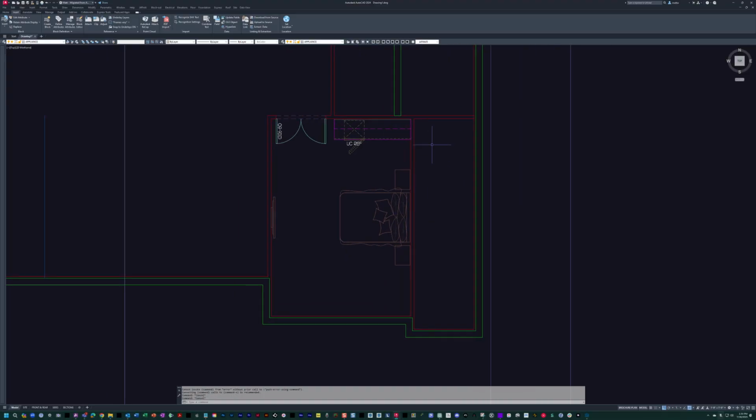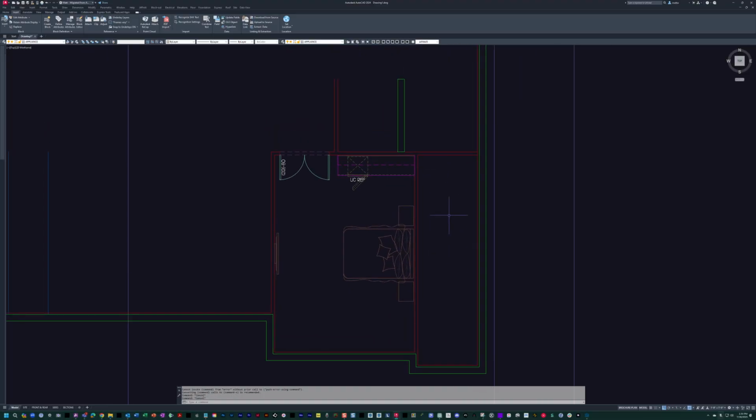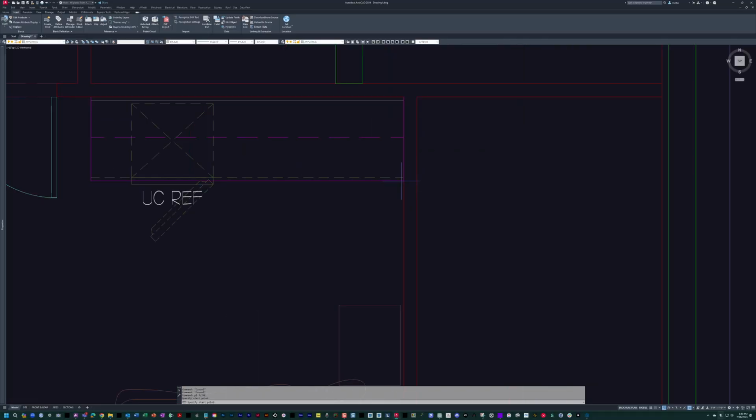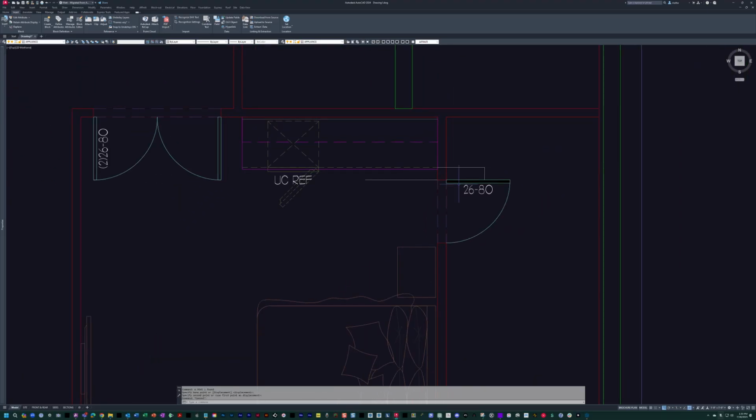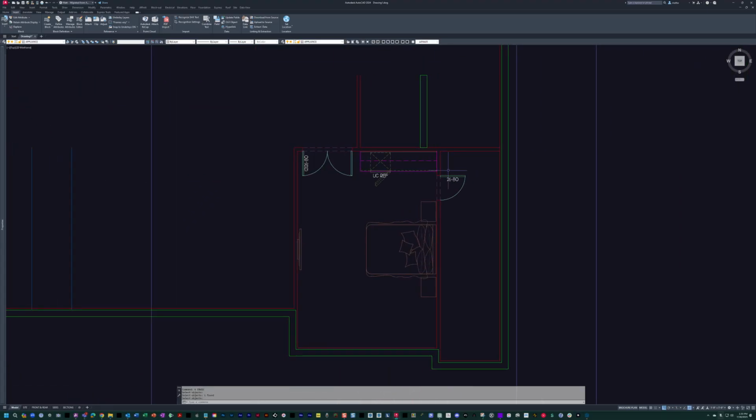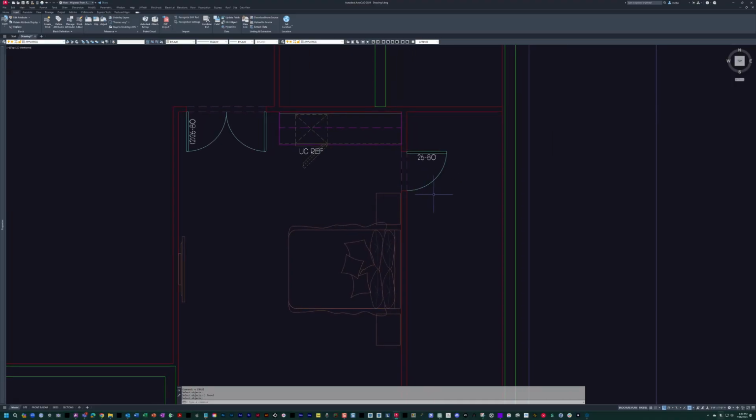I know we have a bathroom and a closet over here. I know already if this vanity is going to be here, again, I want a 6-inch jamb, so let's throw a door in here and see what happens. Maybe we'll have the door open the other way. Grab this and place this here. And yeah, we're clear. We can make it. It's a little tight, maybe tighter than I generally would want, but it's fine. It works okay.